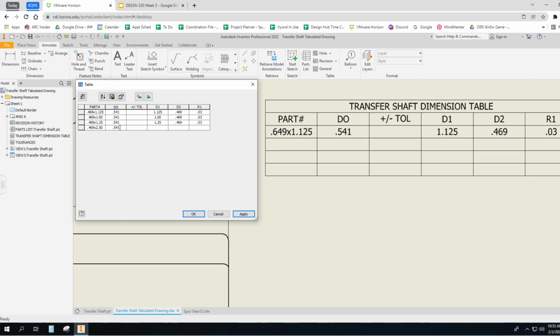Yeah, we just copy those numbers in, but not the first line. The first line we take it from Inventor, and the rest we copy. Right, because these are tabulated values that the engineer gave you. The engineer said I want one that's 1 long, 1.25, and 2.5. Now you're putting your data in.